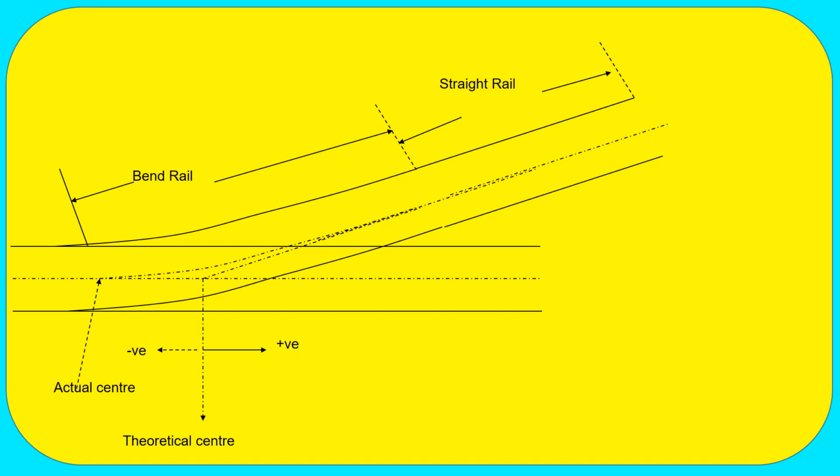Now for high speed we use overlap type turnouts and overlap type crossovers. So all are overlap type. Initially there were cross type and knuckle type. It is better to avoid this type of turnout and crossover, because it affects the movement of the train.